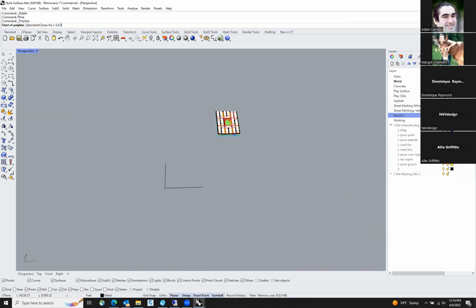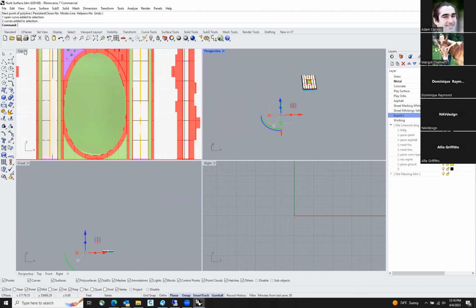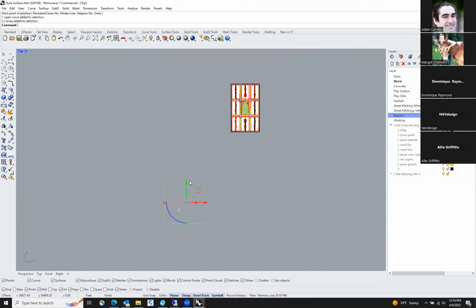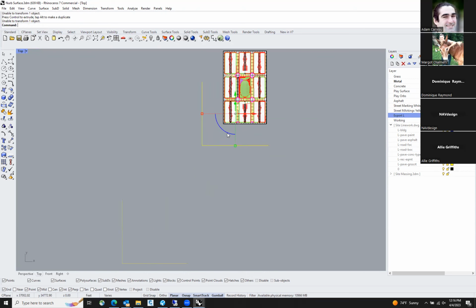And we know that 000 is pretty far away, and Lumion will not render that very well. So I always make an export L adjacent to our model. I'm going to move this one a little bit closer. So then in Lumion, your 000 will be right here.